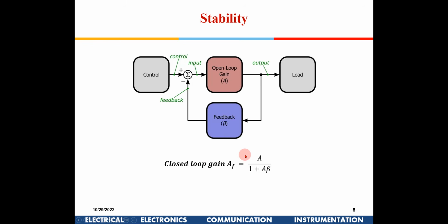Let me go back to this circuit. Suppose there is no signal out here. There will be some noise available here, and this noise will be of the entire frequency spectrum. So at some particular frequency, the signal goes from here to here, and then comes back here, making a 180 degree phase shift, and it has also got a positive gain.